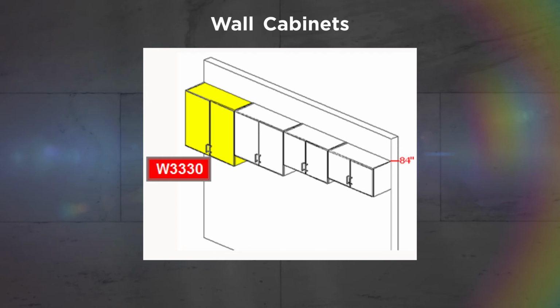The most popular cabinet height in a standard kitchen is 30 inches. When it's placed 18 inches above a 36-inch high counter, the cook has easy access to everything stored on the bottom and second shelf. Shorter cooks may have to stretch a little for items stored on the top shelf. This is a good location for items that are used less often. Since this height is so popular, it's not uncommon to find 30-inch high cabinets available in 3-inch widths from 9 inches to 48 inches. Frameless cabinets may not have a 45-inch or 48-inch option.